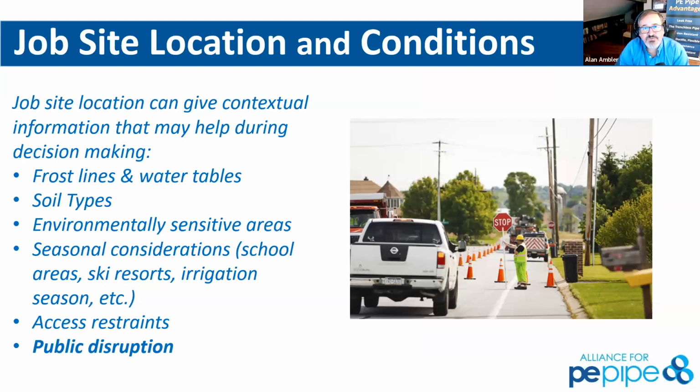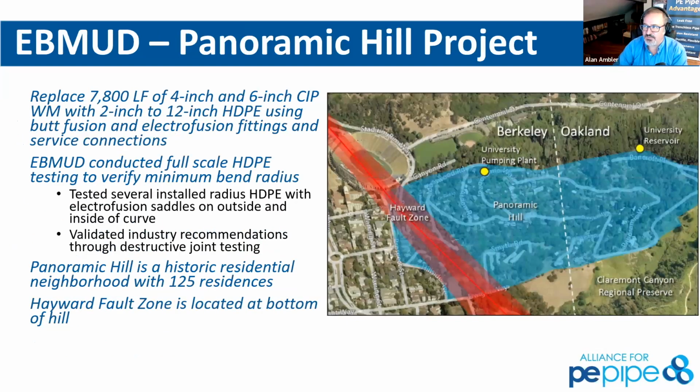Sometimes the timeline schedule for trenchless projects are shortened fairly dramatically by being able to take advantage of the higher productivity, in which case we can take projects down from longer lengths of actual full bypass, full road shifts and traffic barriers down to simple outages from 7 p.m. to 5 a.m. at night. Put that road back together, let the traffic go through it, and then maintain exactly what we're preaching with this smaller schedule. So here we're jumping right into the case studies.